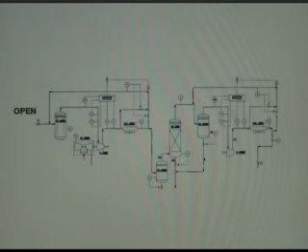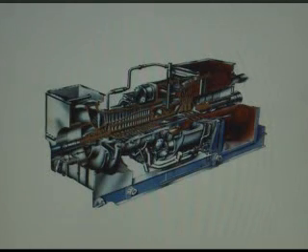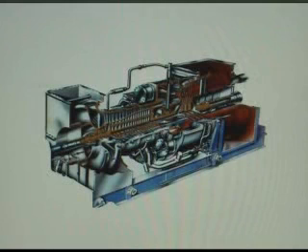This is now a high-pressure gas source, which is now flowing into the process loop through the compressors, turning them into an expansion turbine. And it ended up spinning the gas turbine up to about 1,500 RPM. And when this axial compressor spins, it's going to pull air. And it actually had enough air velocity across it to pin the operator against the struts that are holding that front bearing in place.